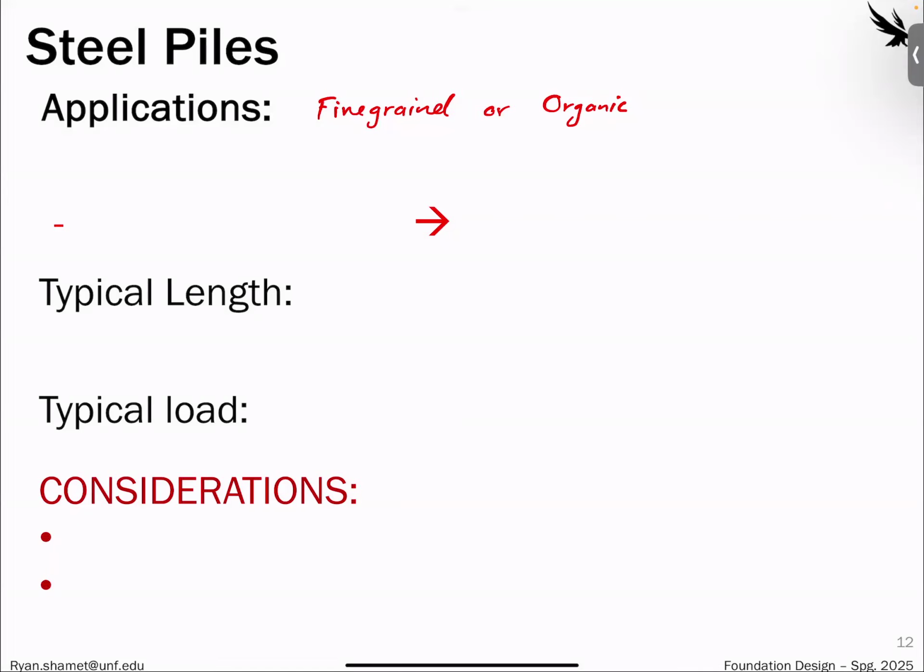So the whole kind of mechanism of this is that the pile's smooth surface will stick to the clay and the silt. So you want to meet the fine grained soil with something that is more smooth, so you have that interface and you develop that adhesion for capacity. All right, that's supposed to move down in the arrow there. I wrote it a little small, but yeah, that's what that arrow was for.